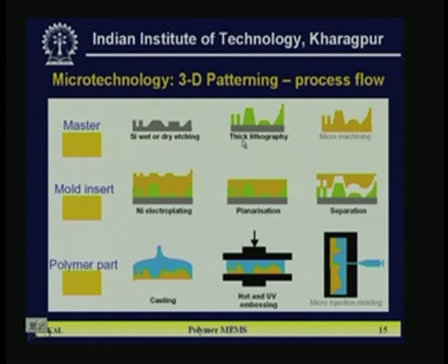Now, the second one is a thick lithography, where along with some steps you may get some bend with certain gradual corners. But if you go for micromachining with certain techniques, we can get a bend like that, because I told you that round shaping you can make with small squares also, but gradual bending or curvature is possible using the polymer kind of thing, which is shown in the second row.